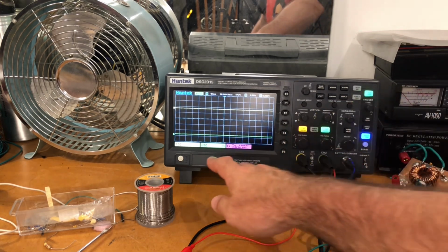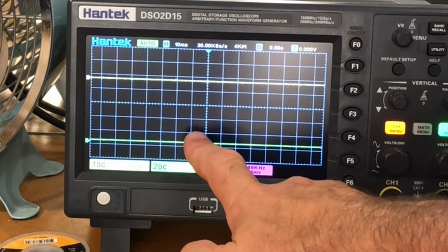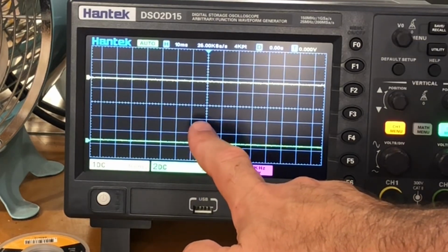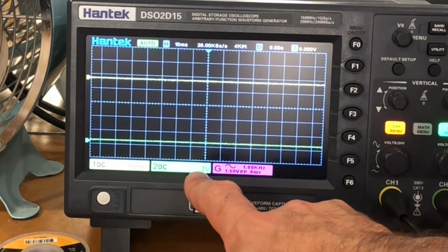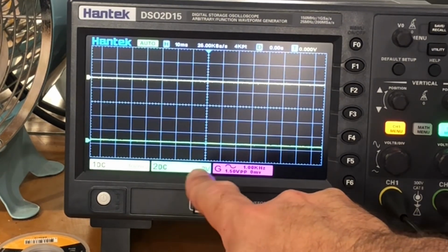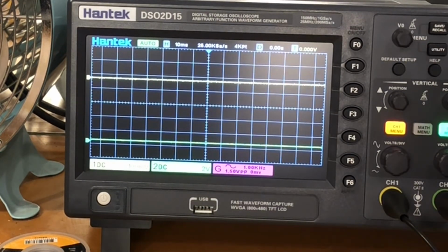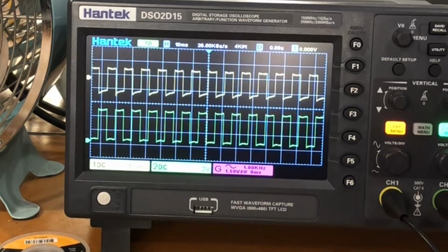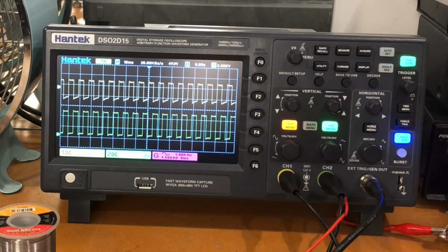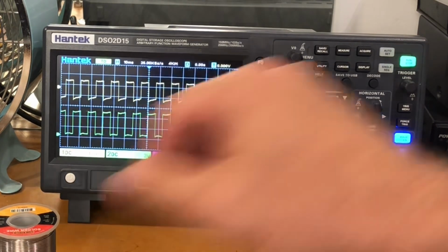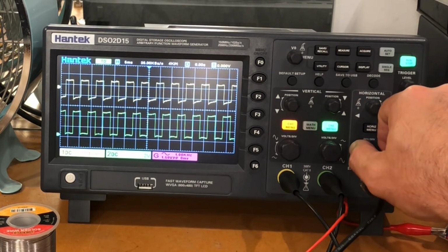So if you look at the scope here, the input is set to 100 millivolts per division. So every time you cross one division here going vertically, it's 100 millivolts. This green is on 2 volts per division. So it's a way higher voltage per division. Watch what happens when we switch it on. As you can see there, these look like they're almost the same size. I'll just play with the frequency here. Let's change it. Yeah, there we go there.